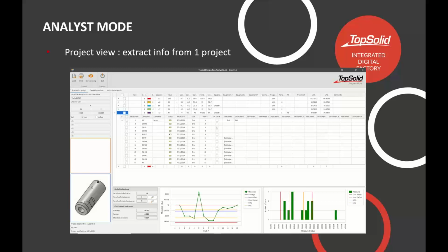And maybe you're manufacturing 40 parts, and for the 40 parts, you have to inspect every 5th part. Okay, so that's what you're doing. You're checking every 5th part, and you can see across the range of checks where maybe the part's falling out of tolerance, or it's getting in the danger zone of falling out of tolerance, so that you can adequately adjust compensations or whatever in your manufacturing process.